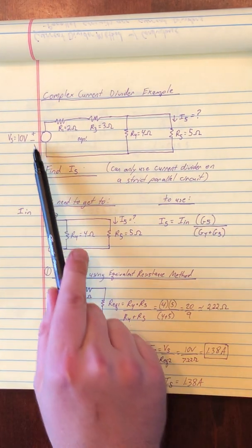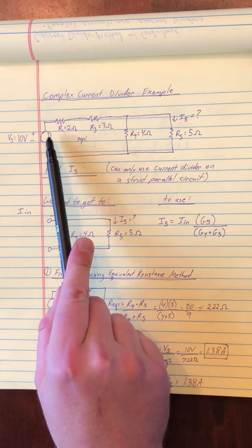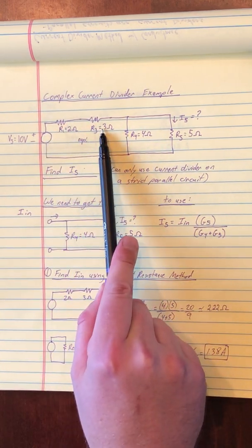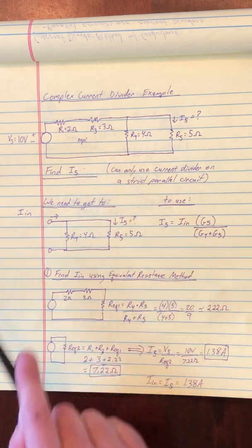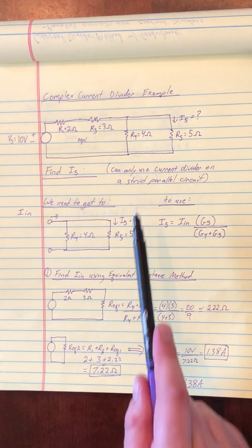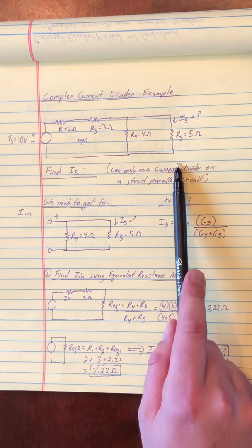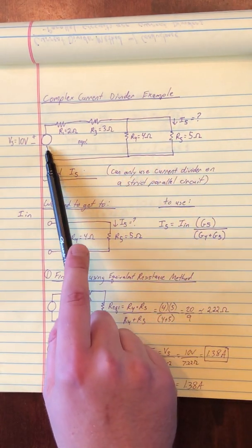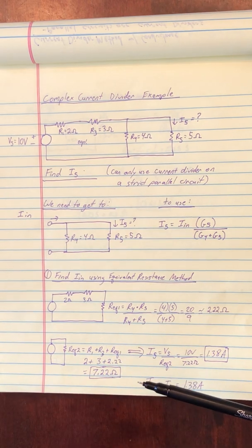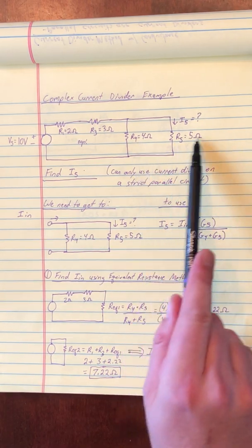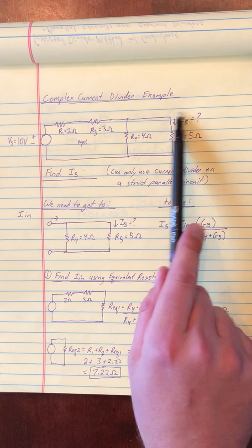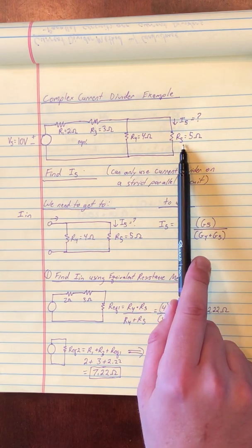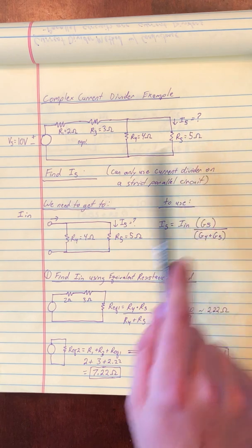And so what we have here is a source of 10 volts, and then we have two resistors that are in series with the source, R1 and R3. I made a mistake here, and I just started to go to 3, skipped 2. And then we have a parallel element here where we have R4 in parallel with R5 before we return to the bottom node beneath the source. And these have 4 and 5 ohms respectively. So what if I wanted to find the current through the path of R5? And so what is the I5 current?